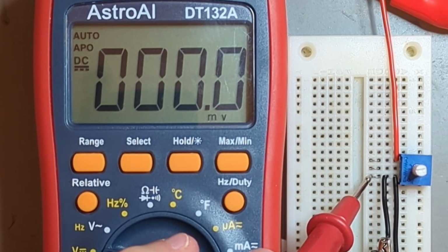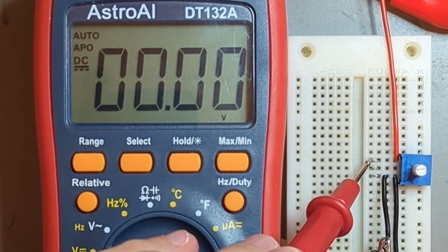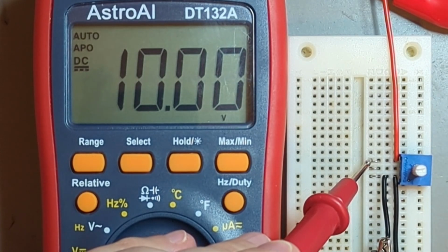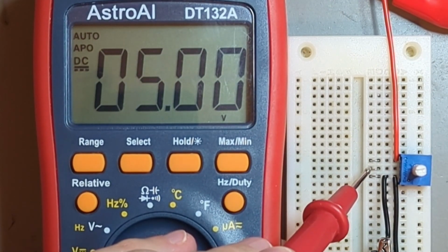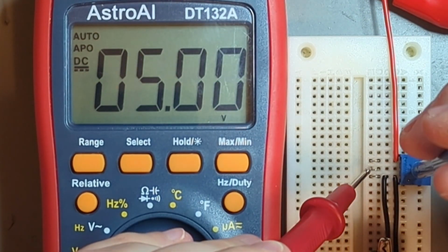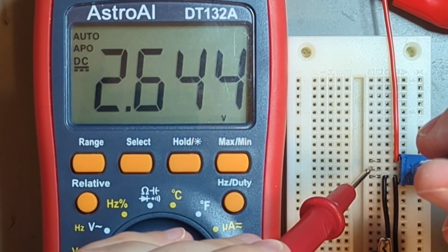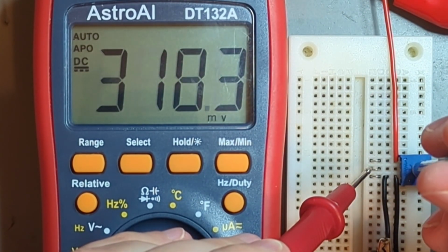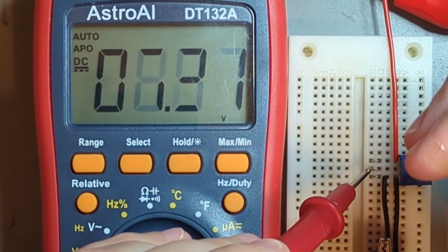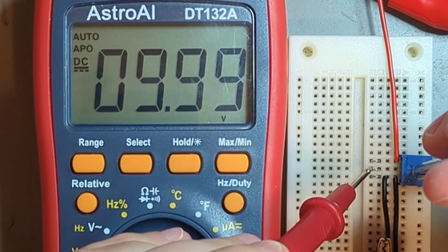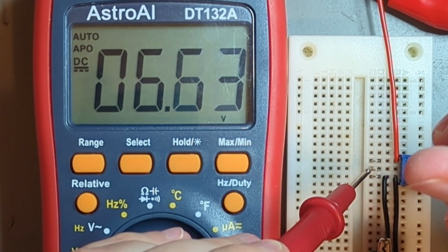Here's a real potentiometer, and I'm just going to be measuring the voltages around the circuit. You can see that I've placed a 10-volt supply across the outer terminals of the potentiometer, and the center terminal is measuring 5 volts, which means my wiper is in the middle position. Turning the wiper clockwise in this case reduces the voltage down all the way close to 0 volts. Turning the wiper back counterclockwise, we can see that voltage go up and up all the way to the supply of 10 volts. So the potentiometer is a really easy way to get a voltage anywhere from 0 to VCC that you can dial in by just turning the knob.